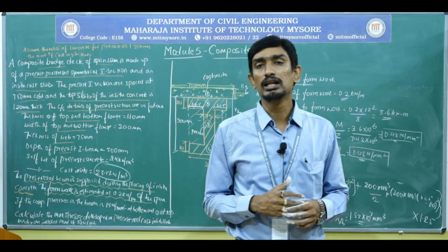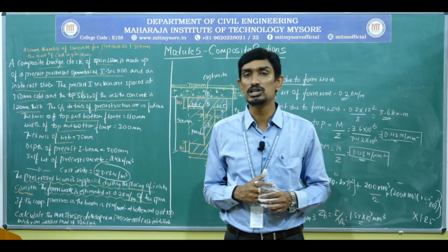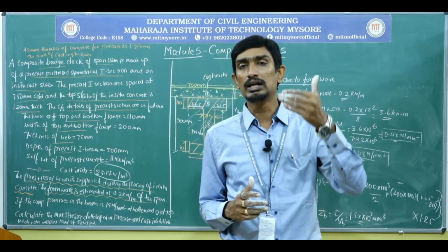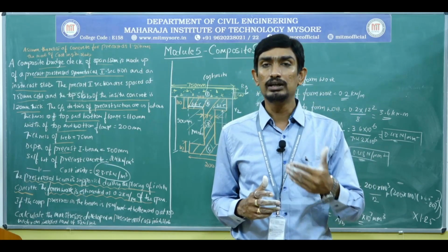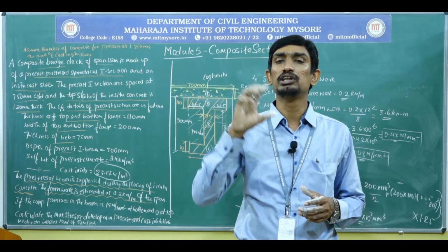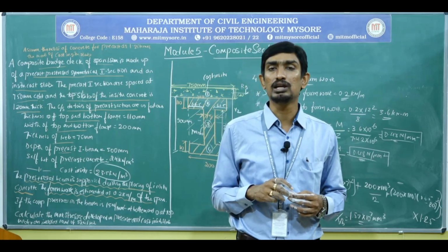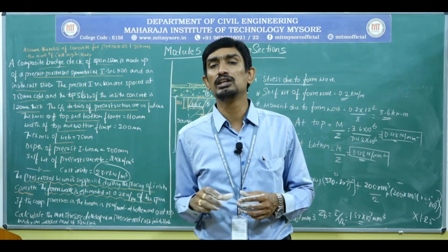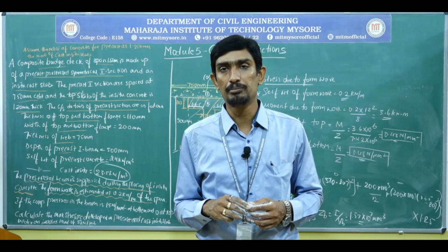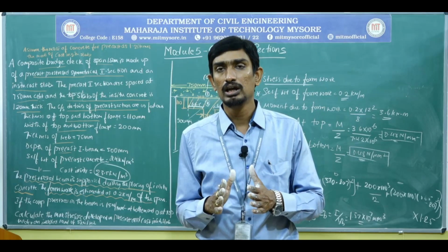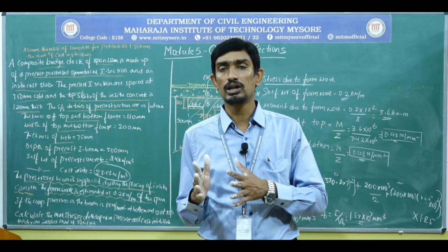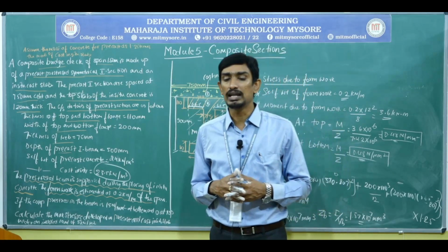While calculating the stresses due to the live load on the composite section, while calculating the Y bar, Y top, moment of inertia, in all those things, in the precast area we need to multiply by this 1.25 modular ratio. Did you get my point? So this is the change from the last problem we solved to this problem. Like this we need to go ahead with the analysis.